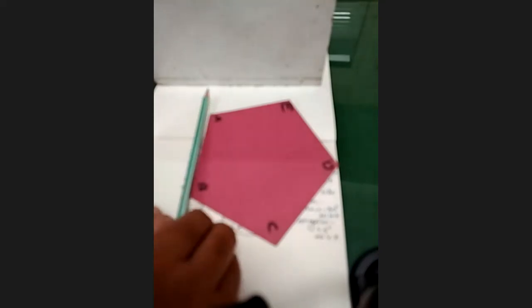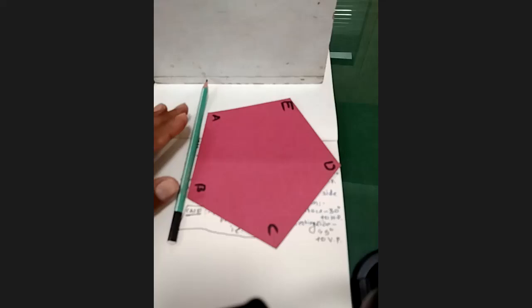What will be the front view for this? If I keep it here, then at this position, what will be the front view? Taking the projection from B and A, suppose here, you are going to get a single point. That point will be appearing on the XY line, right? Got it? Similarly, take a projection from points C and E, you will get another 2 points here. Meaning a single point will be representing 2 points.